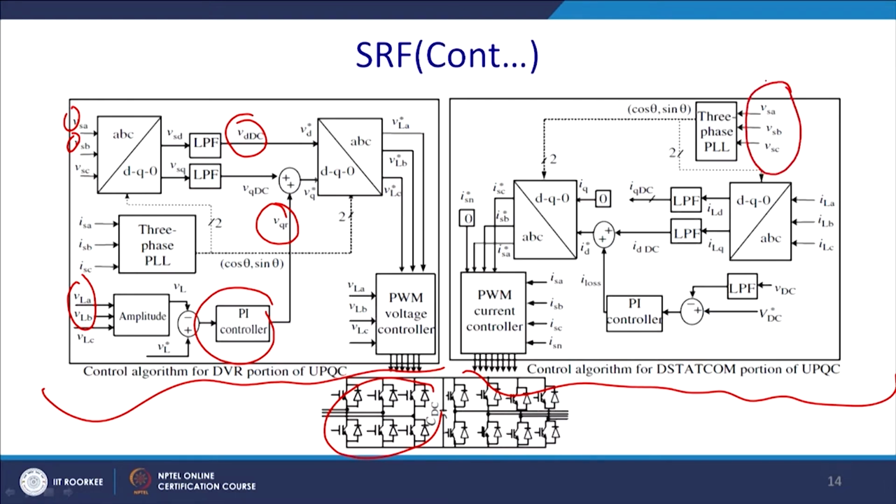So, from VA, VB, VC we get the PLL and we get ILA, ILB, ILC. So, ultimately you have Id, Iq as well as I0 in case of the zero component current. The zero component current is fed through as it is and passed through the low pass filter, and you know that actually Idc should be 0. For this reason you set Iq equal to 0, and here we require to maintain the DC bus voltage. For this reason it will take a little bit of real power.